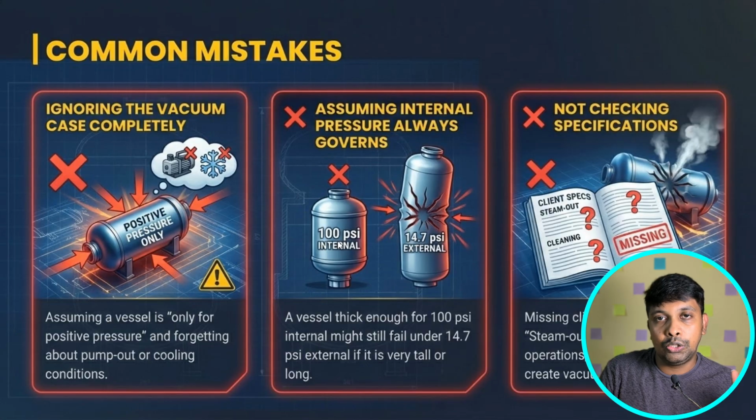Next, we always assume that internal pressure governs the vessel. Sometimes yes, it is true, but if the vessel is too long, then the external pressure will govern more than the internal pressure. So if the vessel is long and thin, we have to calculate the external pressure.